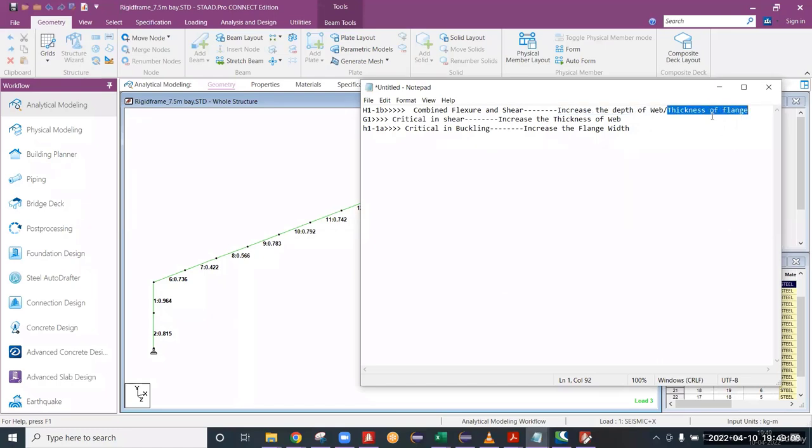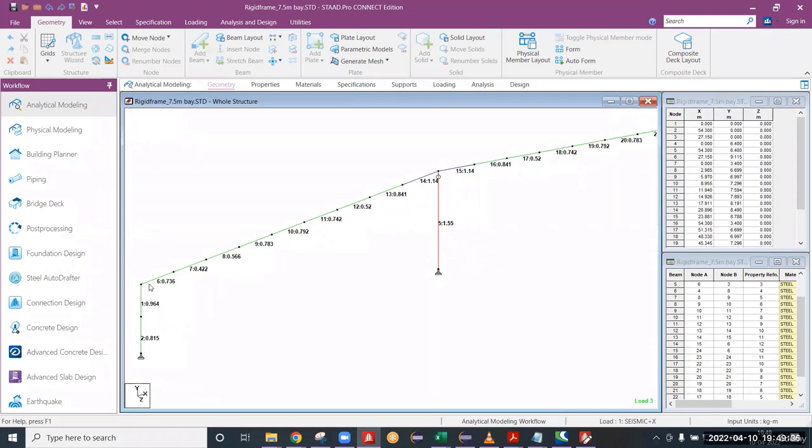Just now I told you, increasing the thicknesses will tend to increase the weight. An increase in thickness anywhere, flange or web, tends to gain more weight. Instead of that, you have to try to pass the section by increasing the web depth only. Anyway, member 1 is passed here, so it is around 1. So if you observe here, what is the ratio here?